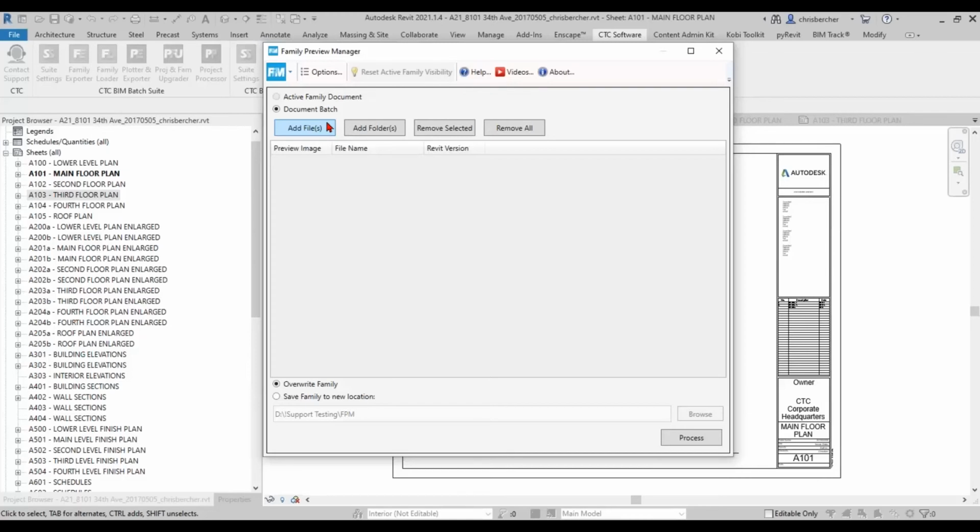So if you've got all of your face-based objects you want to show as an elevated item, or all your wall-hosted items should be elevated, so doors and windows and any other opening, maybe there's wall-hosted cabinets that need to be elevated. We could set up a template that will adjust those in that fashion.